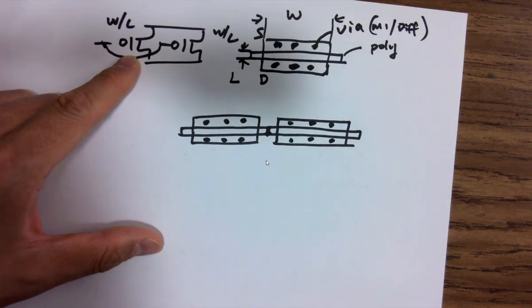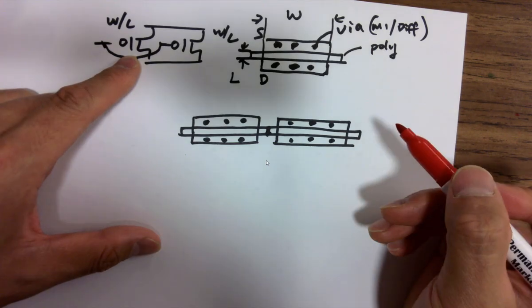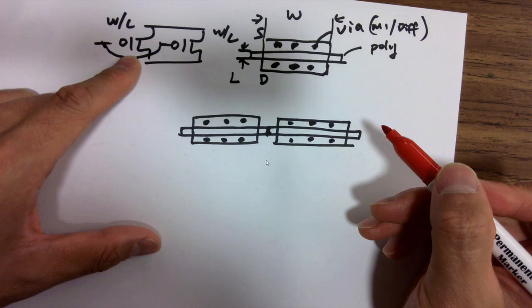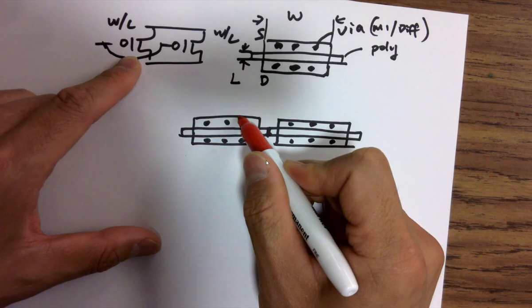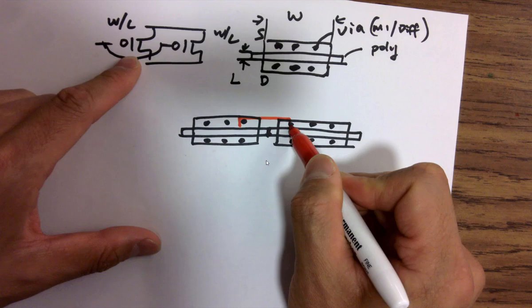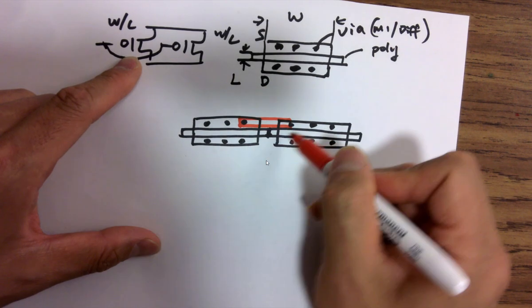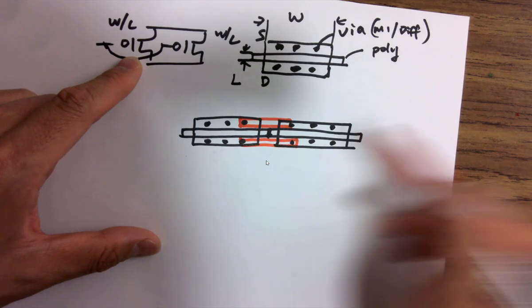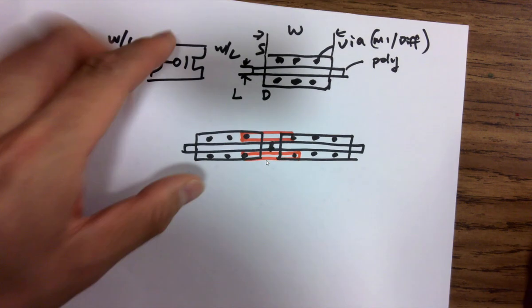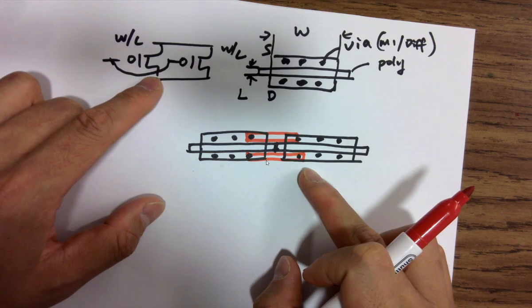Drain to source. How? Using which layer? Metal one. Yeah. How? Through vias. Just draw a box. Maintain the same width, so it's not overshooting. It looks weird otherwise. Just make it nice and do this, right? Just overlap, so you've got these shorted to each other. Do they match? Yes. Okay.